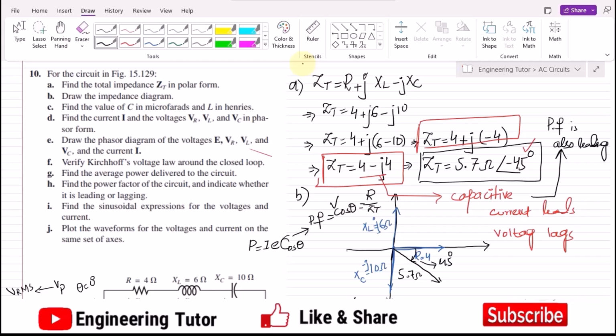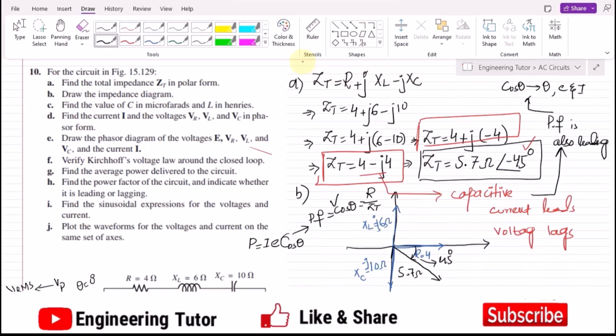leading here. Okay, so for this part we have to find the power factor, which is from cos of theta, where theta is the angle between E and I, or we have to find the ratio between the resistor and the total impedance, using their magnitudes, and we will see that the power factor is known. After it, to see whether it is leading or lagging, we have to see whether the circuit is capacitive or inductive. As the circuit here is of capacitive nature, the power factor will be leading here.